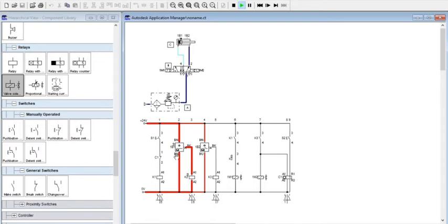When the magnetic field is applied to the proximity switch, the contact becomes open, causing no electrical flow through relay K2. But now we can see the electrical flow through proximity switch 1B1. Then the coil of relay K2 will energize, so the switch K2 also changes from normally open to normally closed.